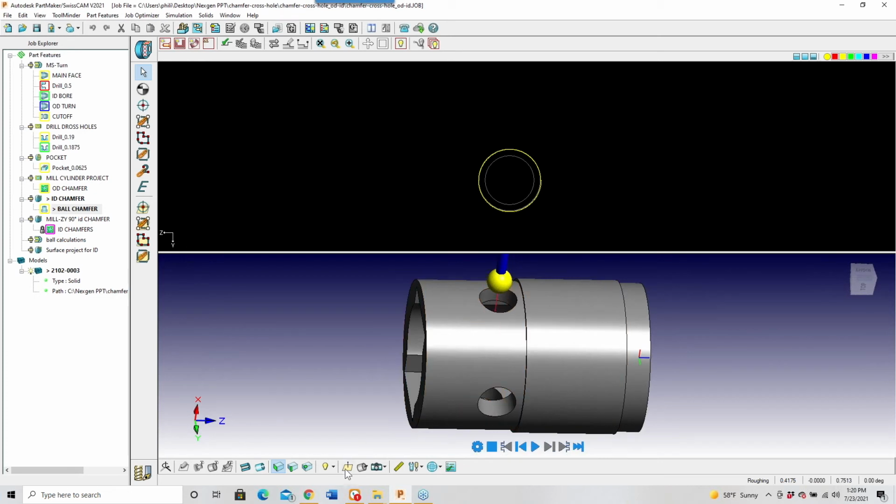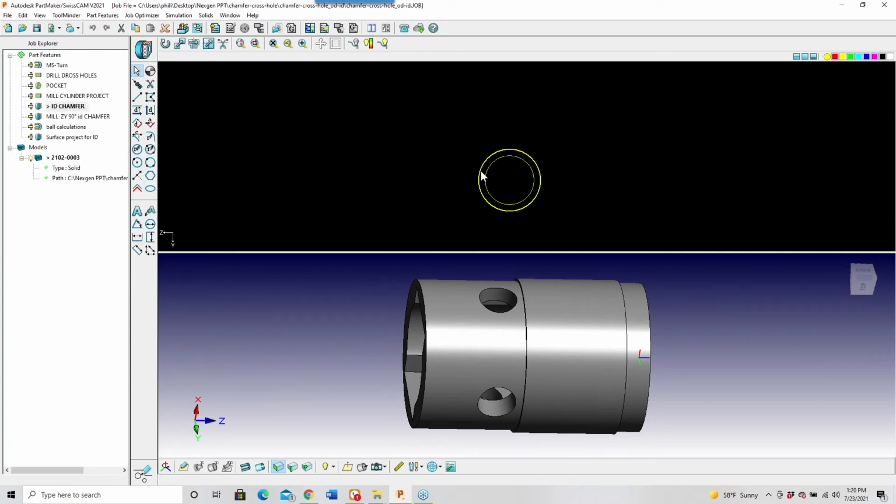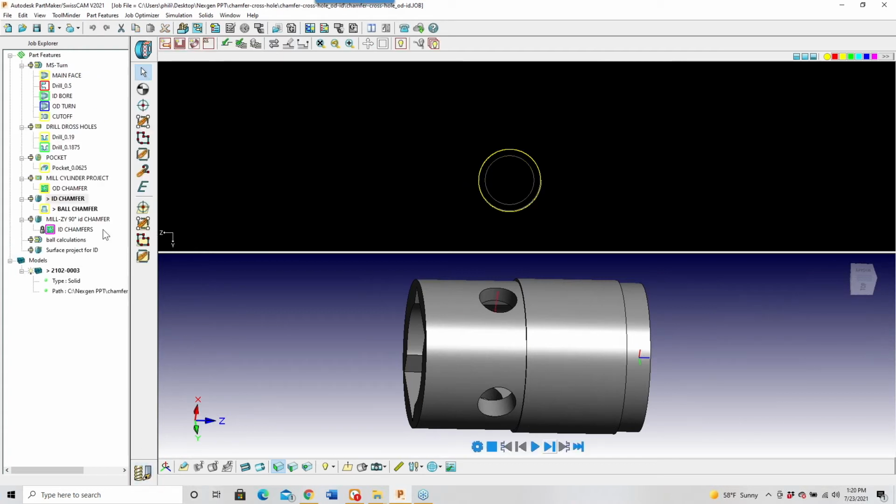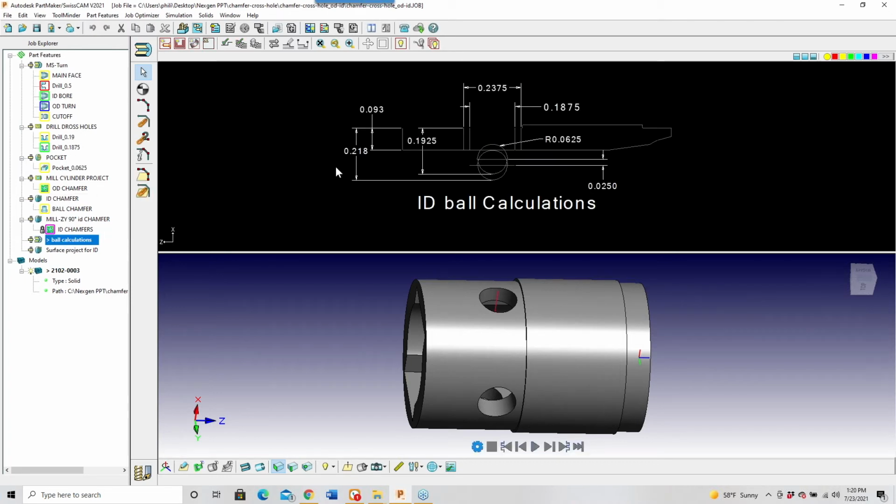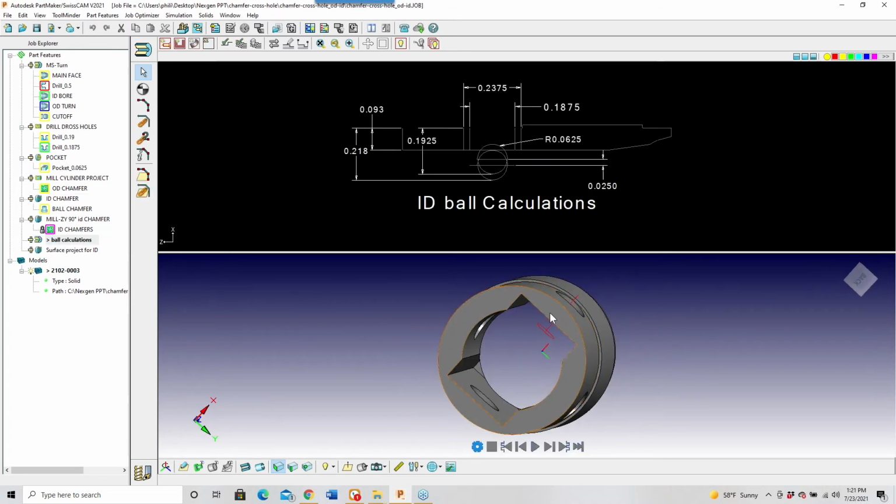Okay, so again, what we want to do is find the diameter of the hole and then offset that value by a number that's less than the clearance between the edge of the lollipop cutter and the edge of the shank. In this case, it was 25 thousandths. And then when you calculate the tool path, you're going to add this thickness together along with the diameter of the lollipop cutter, and then subtract the amount that you offset the original geometry by.